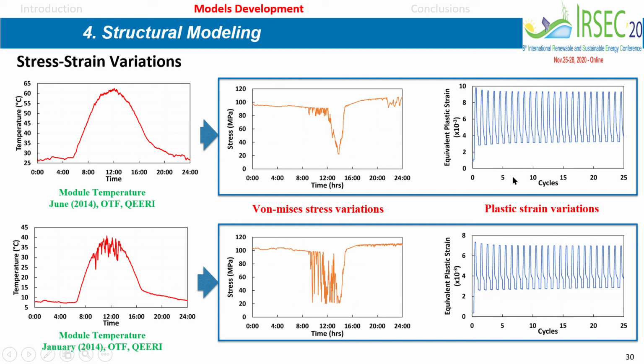We measured the plastic deformation, and as you can see, it is cyclic, and the amplitude becomes smaller and stabilizes. It is established in fatigue modeling that you have to go to at least 20 cycles to stabilize the amplitude of plastic strain in order to use the fatigue model that I showed before. And it stabilizes, in our case, even before 20 days or 20 cycles.